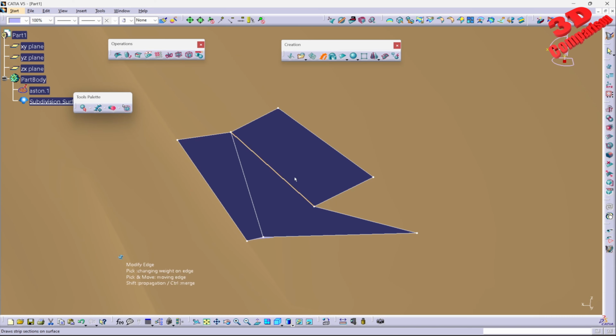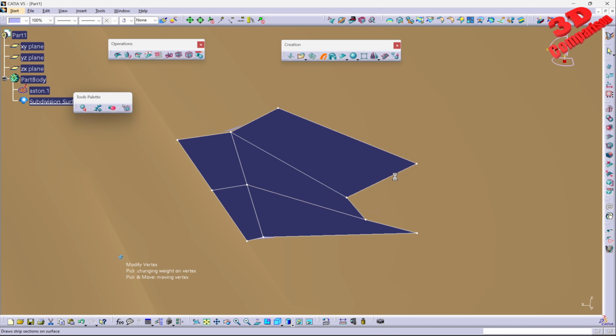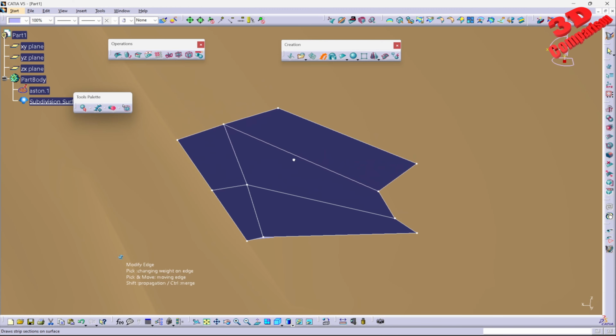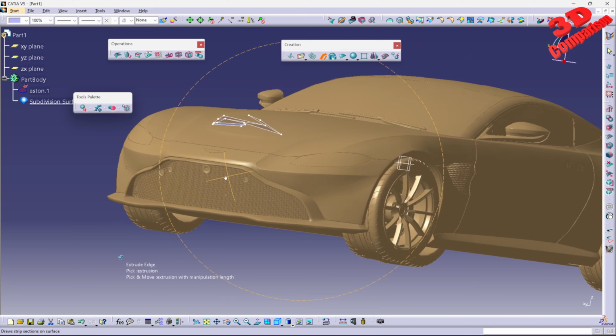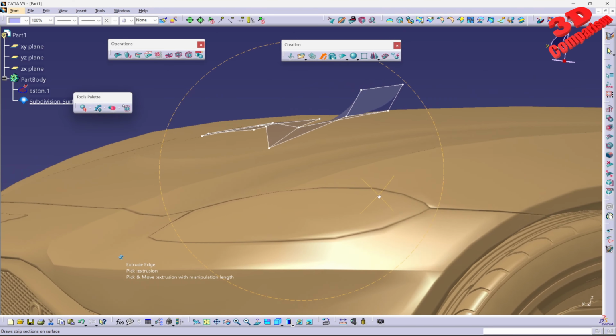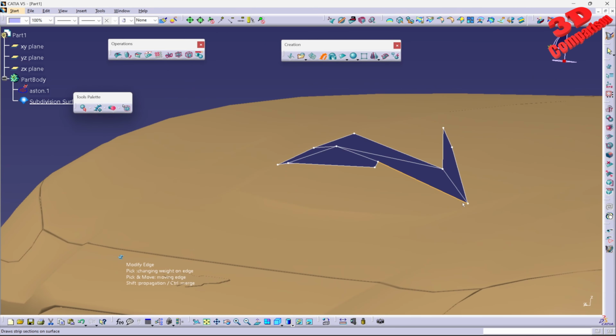I can also add additional geometry. So if I go over here onto the middle, this will add those additional vertices. And we can start moving this around. Now, if I select this edge, for example, if I try to move it, we're going to see that this will look weird, and we have the impression that this edge is no longer added directly onto the surface of the hood, but this actually is. So I'm going to move it all the way over here, and now if I zoom out and rotate, we're going to see that it will be snapped to those vertices from the mesh.